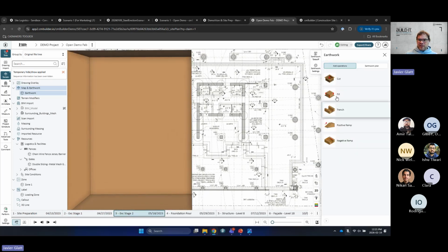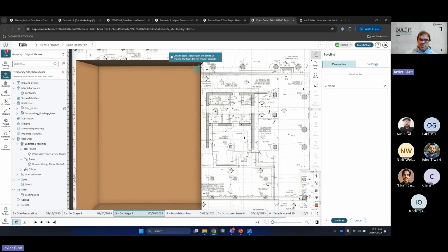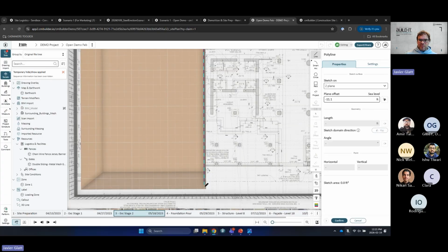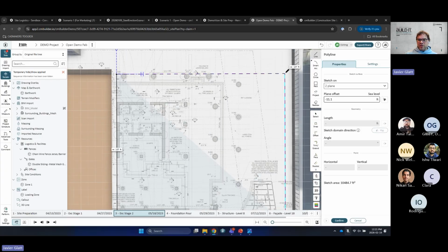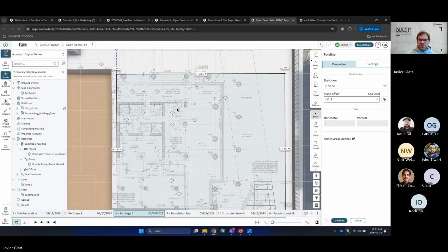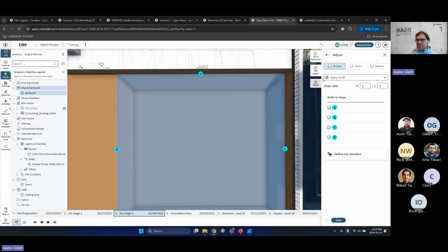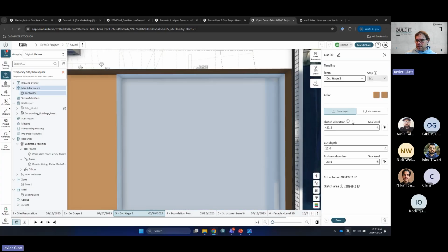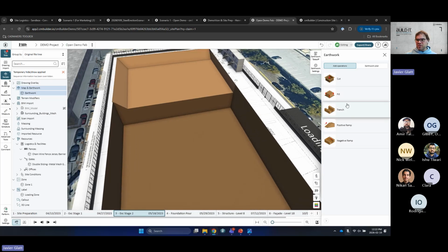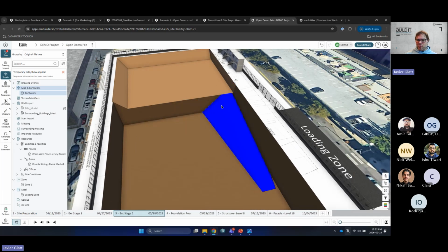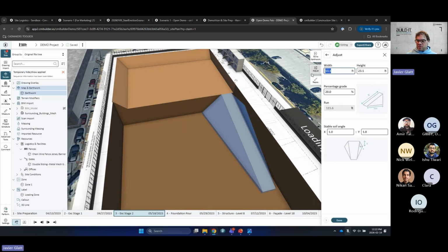And then I'm going to go to my next one, excavation stage 2. Again, it's going to auto save everything I'm doing when I'm active in that milestone. So I'm going to go here, and I'm going to do a second cut. Let's imagine this time no sloping, all vertical shoring, 24 feet deep, just to show the dramatic effect of 2 depths, and change the color. Boom, I got my 2 elevations. And if I need to show a ramp, snap a ramp in, adjust the ramp. Let's go 20 feet wide. The grade, fully parametric, right?